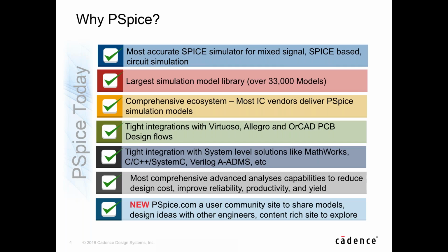In addition, PSpice provides the most comprehensive advanced analysis capabilities to enable customers to reduce the design cost, improve reliability, productivity, and yield. So we'll talk about Monte Carlo analysis, optimization, stress analysis, all of these different analysis types that will help you improve your reliability.